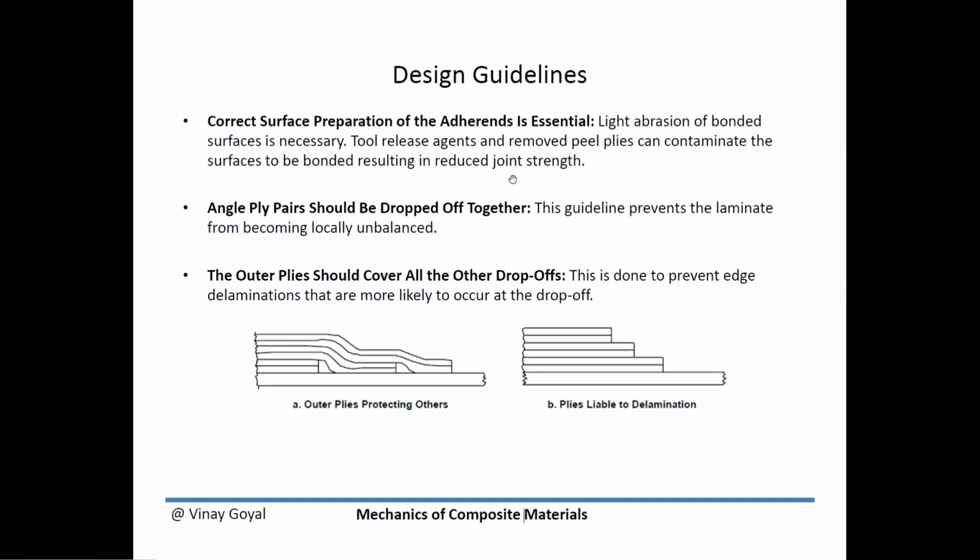Correct surface preparation of the adherends is essential. Light abrasion of bonded surfaces is necessary. I have a whole lecture on bonded joints on YouTube that I invite you to take a look at, and I'll put it in the description of this video at the bottom. I think it'll be a good three-hour adhesive tutorial about this stuff.